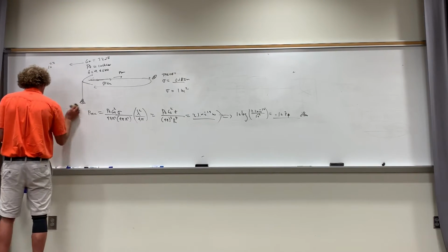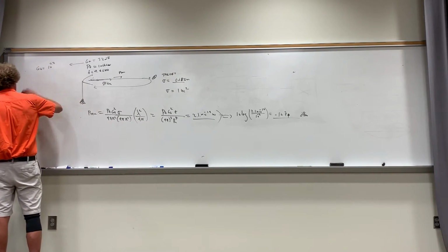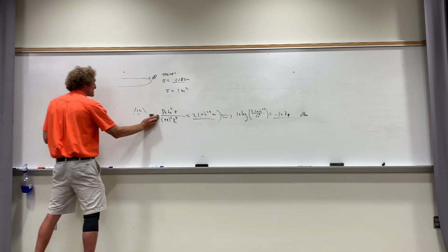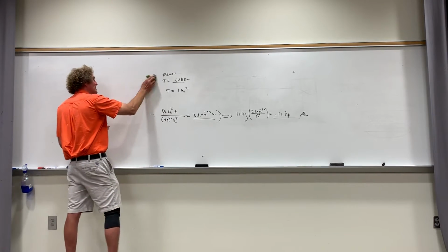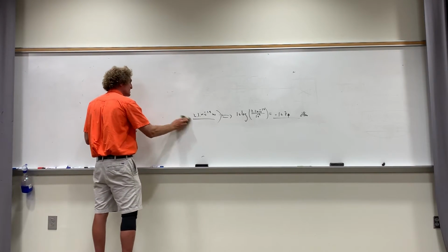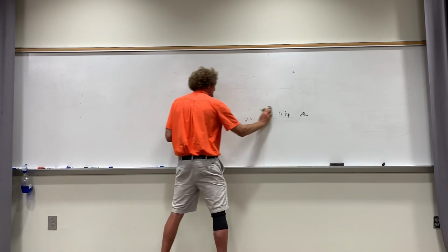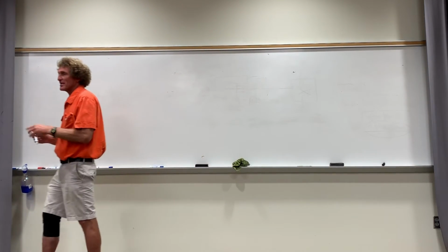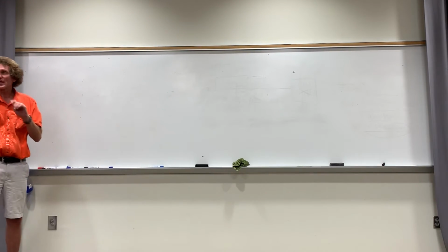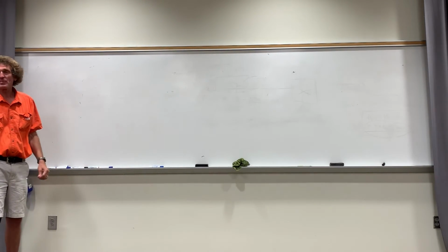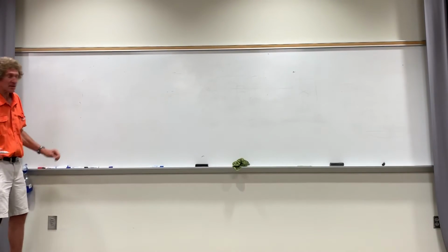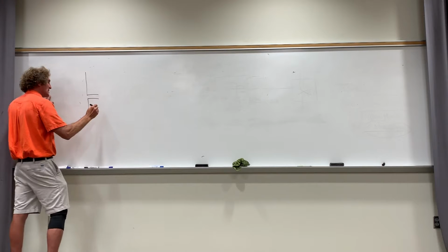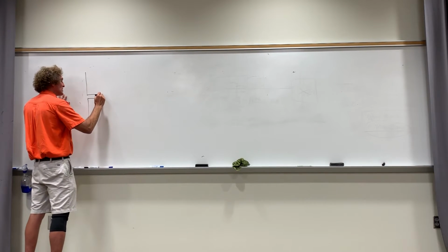Because what it says is consider a lossless half-wave dipole antenna, if the antenna is delivering 1 milliwatt to a match. Oh, delivering. It's not receiving, it's delivering. So you have to find P received, which is where that 2 came into play. If it's delivering that much power to the load, it's not receiving it, it's delivering. That's why I was bringing up that 1/2 P received equation equals V_L squared over 2 Z_L. So with a matched load in place, right?